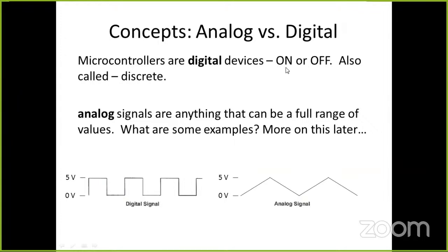We can write code over there in the Arduino, high and low, and we can make that on and off, like earlier we have done for LED on and off. So there are two signals in the digital: one is digital input and one is digital output. If you want to read the status of an appliance or any machine, that is on and off, we are going to read it as digital. And if we want to read any sensor value, whether that sensor is high or low, we can also read it using digital input.